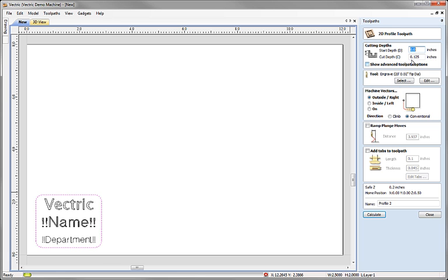And then what I could do here, the cut depth's actually already set, but just to show you how I found that cut depth: for the purposes of this final pass, this cutout pass, I want to cut right through my material, and there's a very convenient way of finding that using what's called the calculate edit box feature in the software.